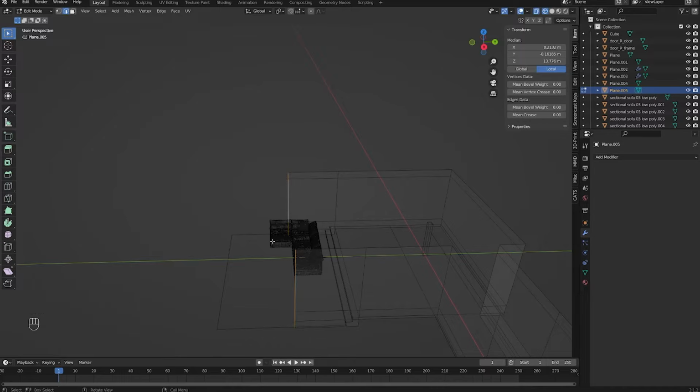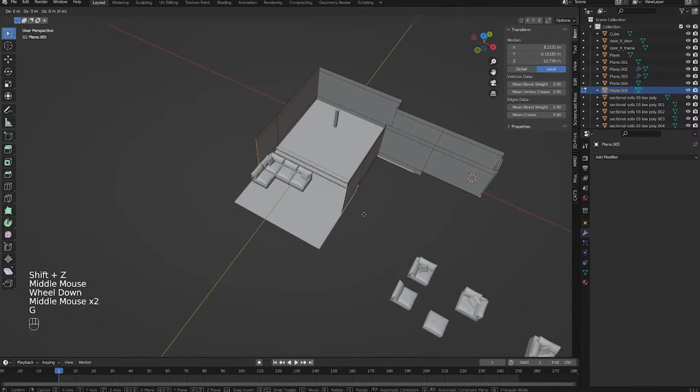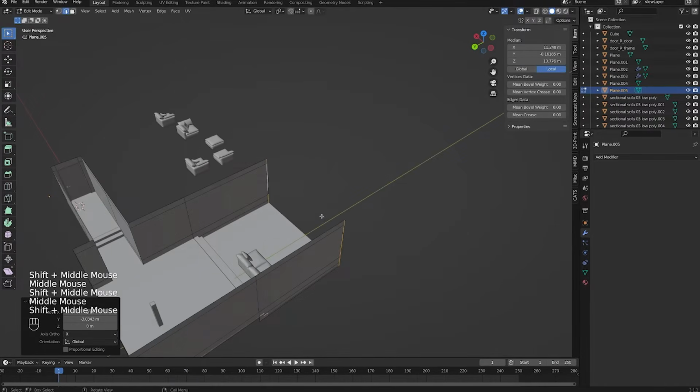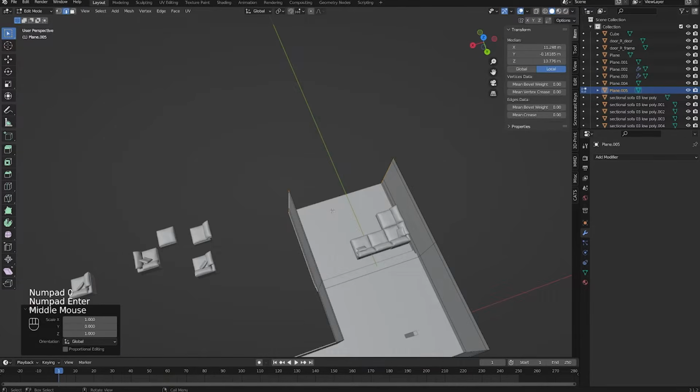And now, because of the way that we've extruded everything and moved things around, by pressing Alt, oh, no, it still does the whole thing. Never mind, ignore me. Select both these edges. G to move, lock it to the Y-axis. Let's bring it here. Now I want to join these, so let's scale in the Y-axis to 0, just to make sure that they are at the same spot and level with each other.